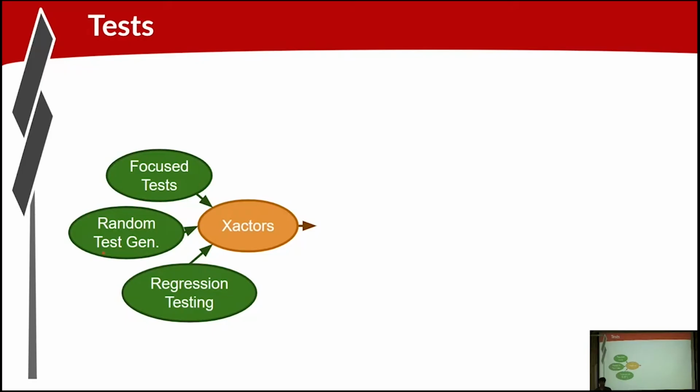We have random testing, and varying levels of randomness in the testing, right? The random testing, of course, is trying to give us a smattering of activity in the chip, where the focus tests may be drilling down into a very specific gnarly corner and trying to exercise something that if you just throw random stimulus at a design, you're unlikely to hit.